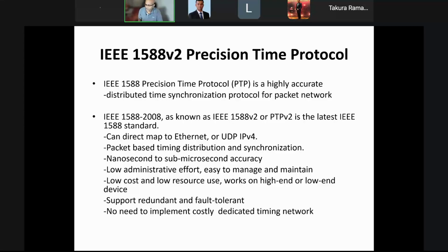But the best practice is on top of Ethernet, distributing by using UDP with multicast for the distribution and time correction. We can use unicast for each and every ordinary clock. So it is possible to implement this with the PTP standard, and to make it accurate up to the sub-microsecond level.